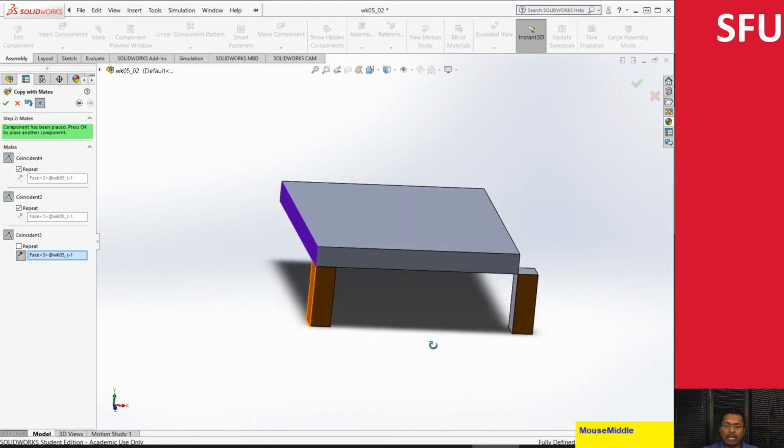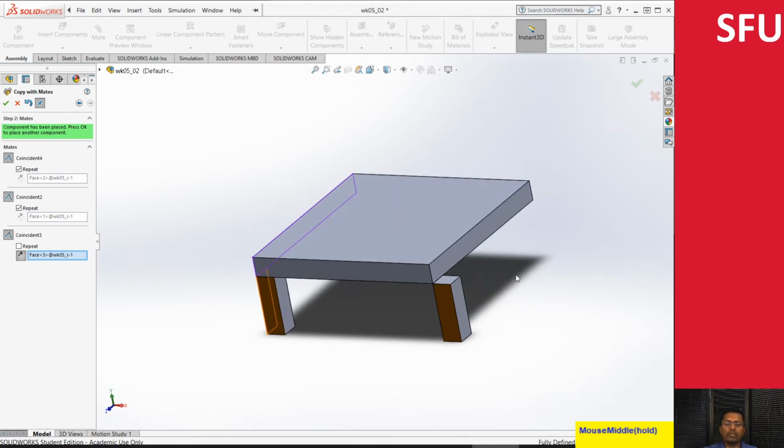Unfortunately, I can still fiddle around with these mates to try to get it aligned exactly. But I found that it's often more effort to fiddle around exactly with copy with mates. So what I usually try to do is copy with mates maybe 3 or 4, or most of the constraints. And if I notice that I'm just going in circles, that it's not aligned properly, maybe I can disable this and then try to flip it. But then I'll notice that I'll just keep going in circles, which I don't want to do. So I'm just going to say OK here.